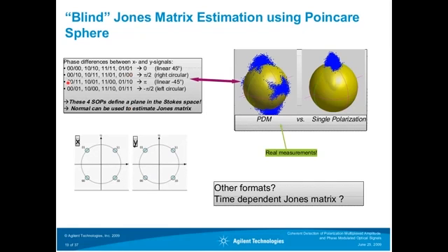If you send out 0, 0 and 1, 1, that's this symbol and this symbol, there's a pi phase shift between the 2 symbols on X and Y, and you end up with a linear minus 45 degrees polarized light. And the same, of course, if you have 0, 0 on X and 1, 0, 1 on Y, you end up with a phase shift of minus pi half or plus 3 pi half.